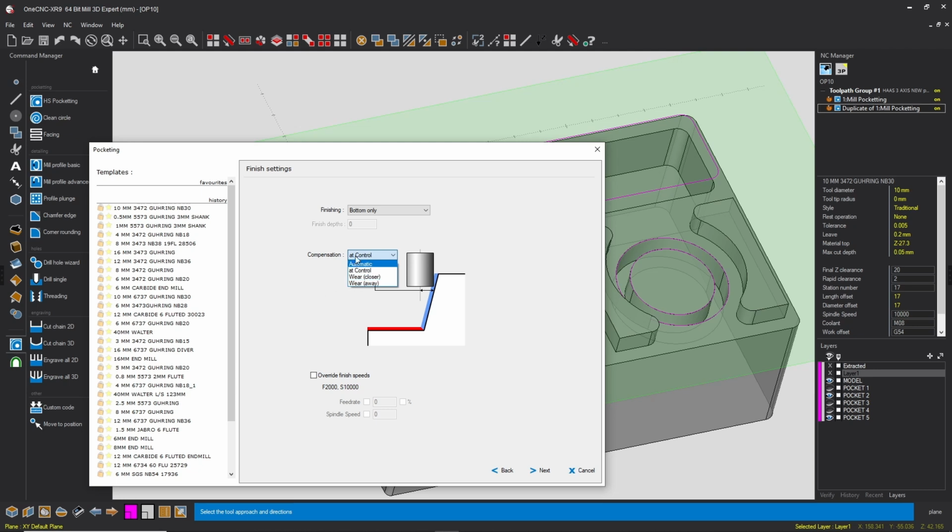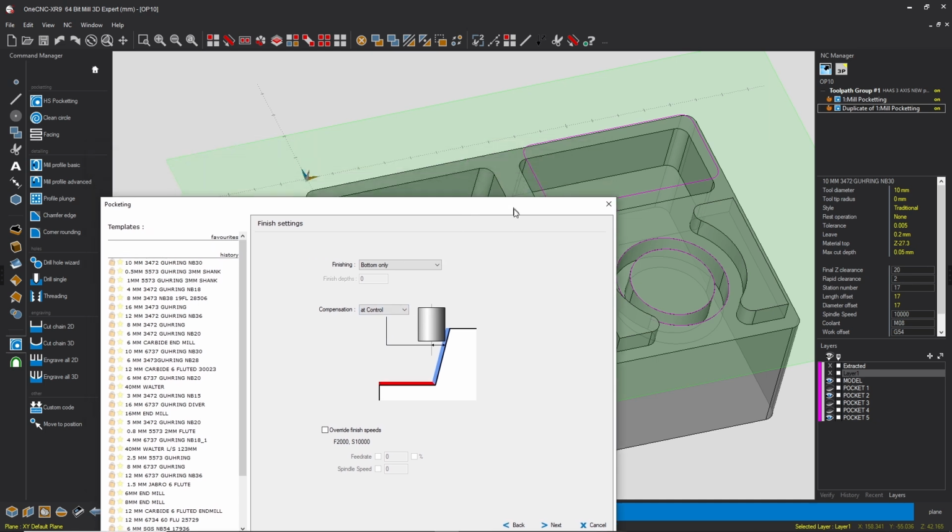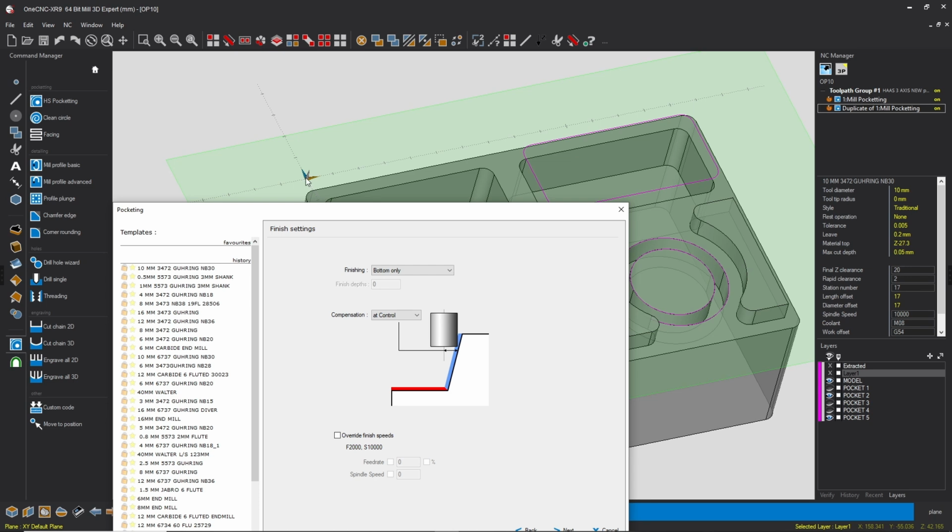Now this is the bit I was on about a minute ago about trying to find out what they all do. So automatic, to put everything in a nutshell, will not use comp. It will just program the tool to go to its finish position. So this wall here, for instance, is 5 mil back from my datum. The tool's 10 mil.